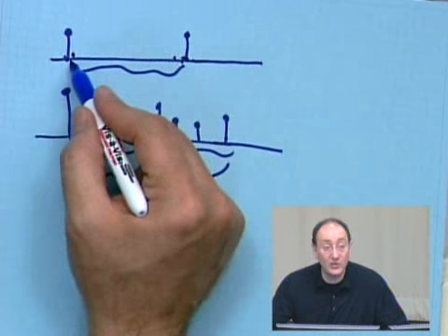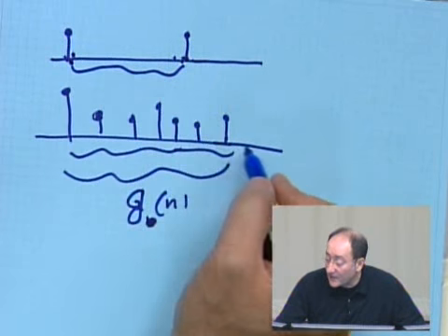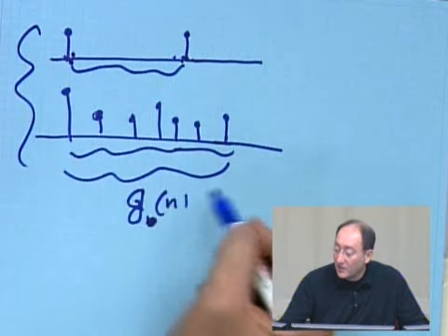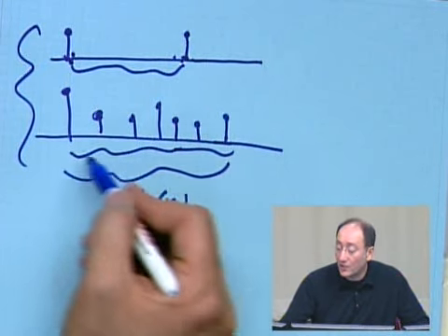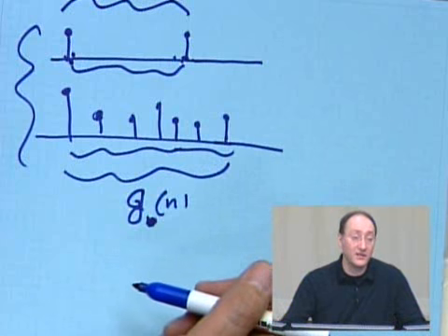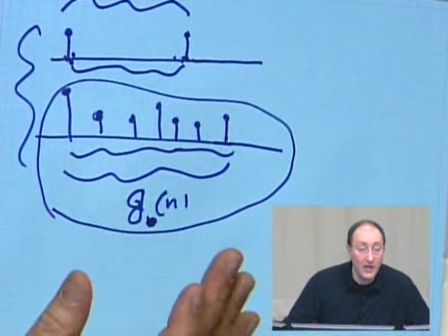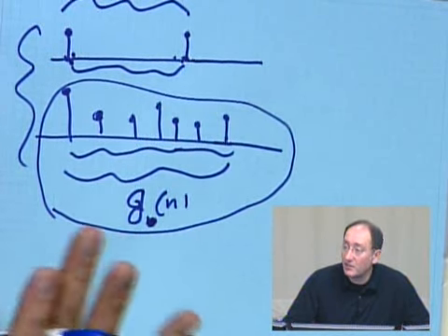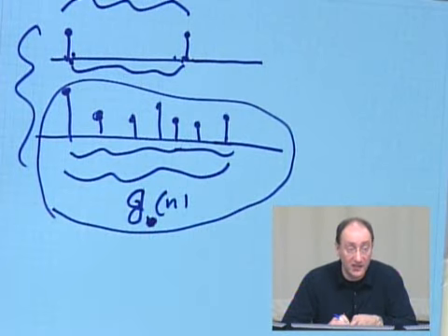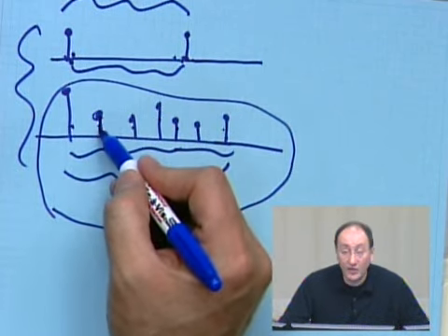If it is less than this, I don't have intersymbol interference; it is narrowband communication. If it is more than this, I have intersymbol interference; I have wideband communication. So in this case, since the duration of the pulse in discrete form is more than the distance between the two symbols, I have intersymbol interference. But anyway, my channel is this thing in discrete form, and I don't need to worry about any modulation, demodulation, or anything like that. With that, I can develop a better understanding. So the channel model is a bunch of taps, and these taps are not fixed, they are changing.